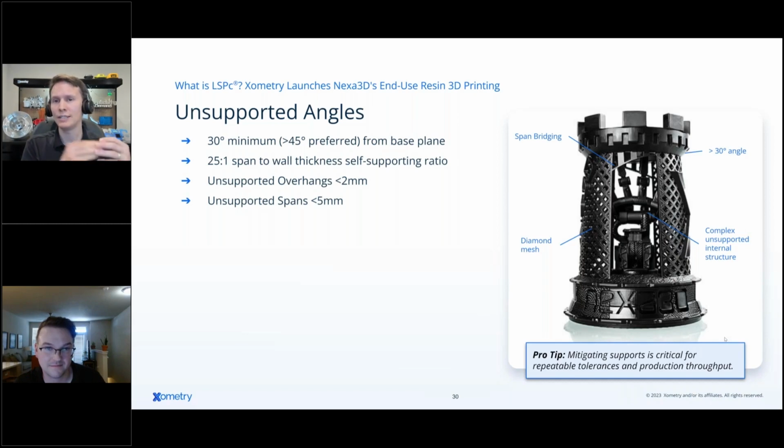So it's the same thing in machining. If you have a thin wall, we'll slow down the machine. We'll make that feature achievable. But if you're moving to a production of 300, we may ask to thicken that up because it will drive costs and will drive risk into the part.